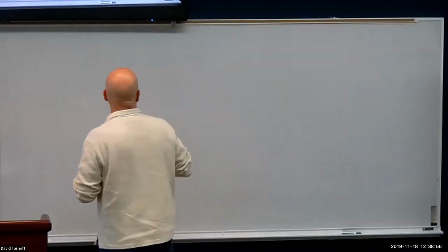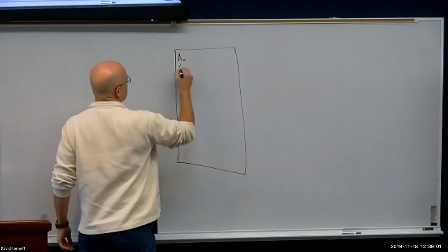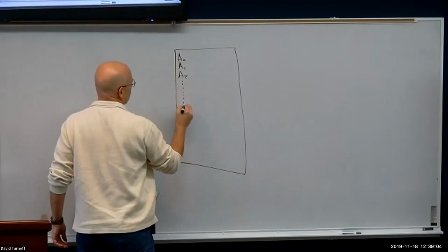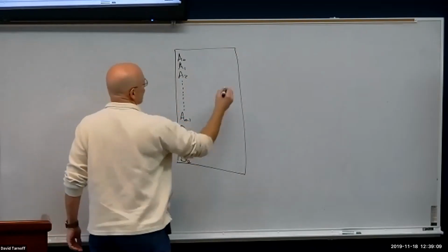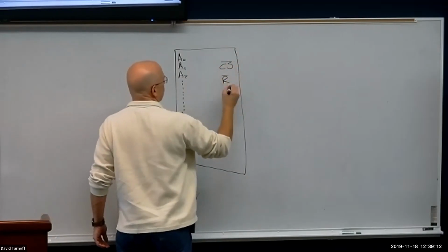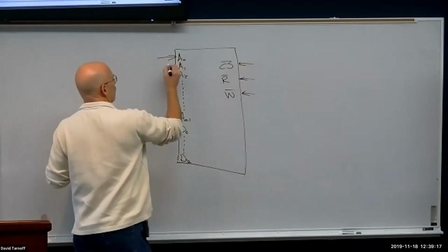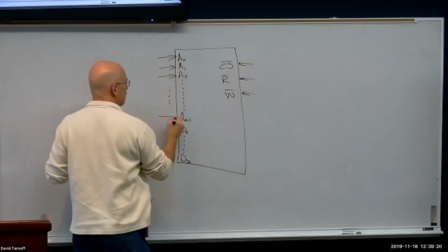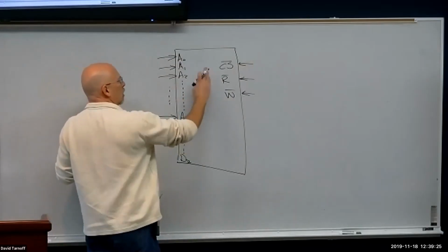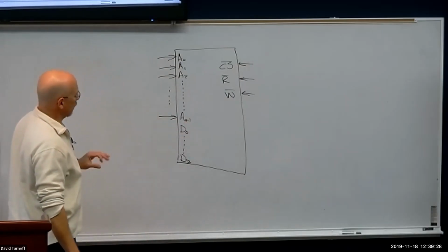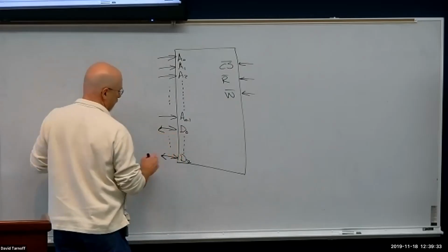Whenever we talked about memory, I said that there were a number of inputs. You had a bunch of address lines, A0, A1, A2, all the way down to AN-1, and you had D0 to D7. And then you had this chip select, this read bar, and the W bar. Most all of these inputs to the memory are actually coming from the processor in order to control the interaction with the memory. The only thing that's two directions or bidirectional are the data lines.